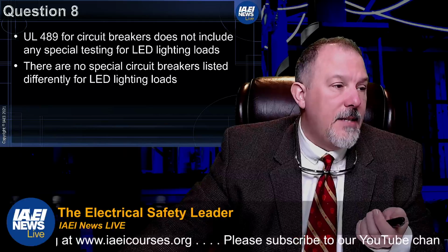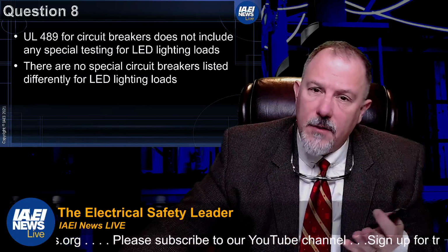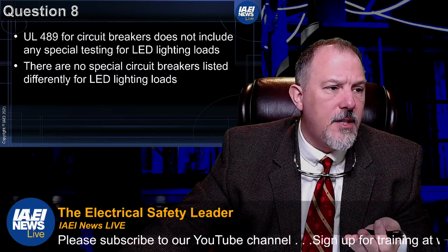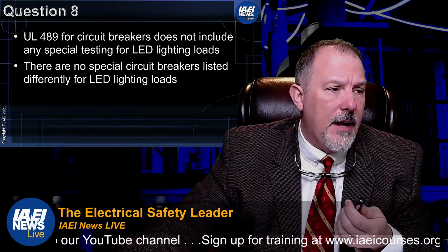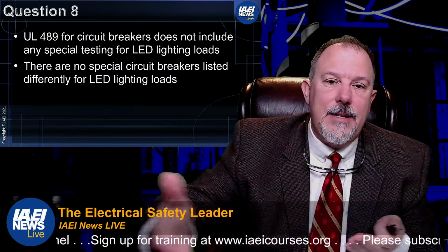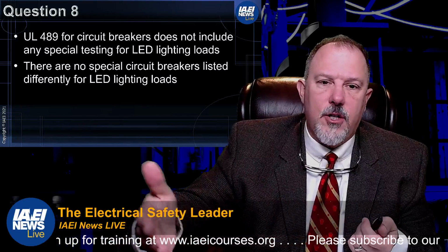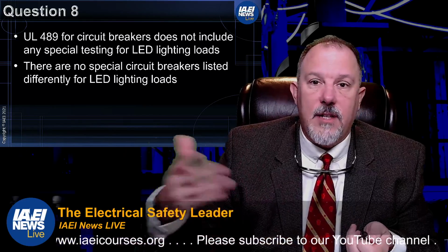I would say take a look at the driver itself, talk to the manufacturer, and understand what types of inrush currents can be expected from those drivers. Remember, the actual LED is on the DC side, so there are no inrush currents on the DC side. Don't ask what the inrush current is on this LED light.